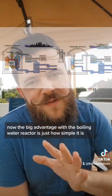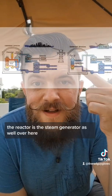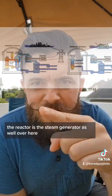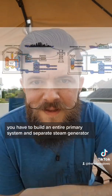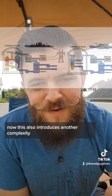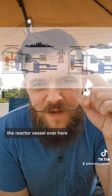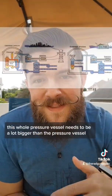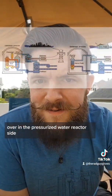Now the big advantage with the boiling water reactor is just how simple it is. The reactor is the steam generator as well. Over here you have to build an entire primary system and separate steam generator. Now this also introduces another complexity. The reactor vessel over here, this whole pressure vessel, needs to be a lot bigger than the pressure vessel over in the pressurized water reactor side.